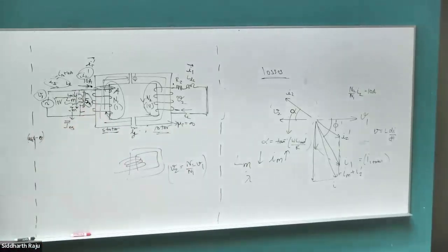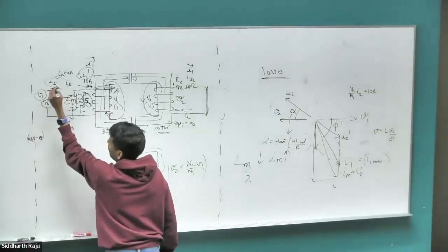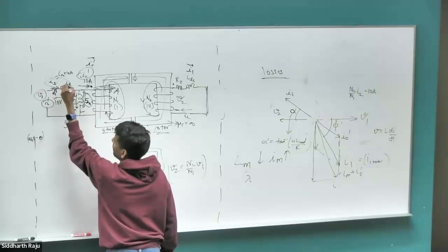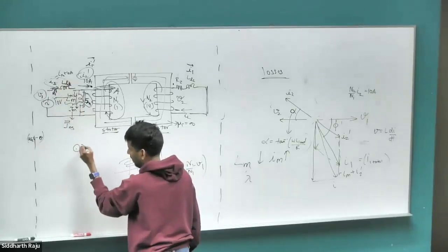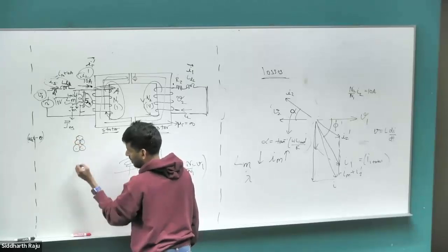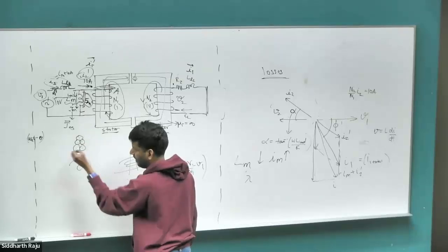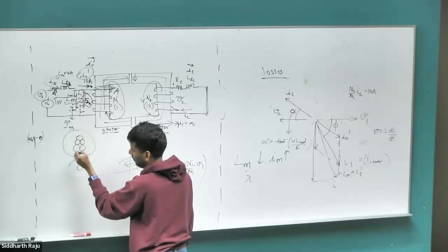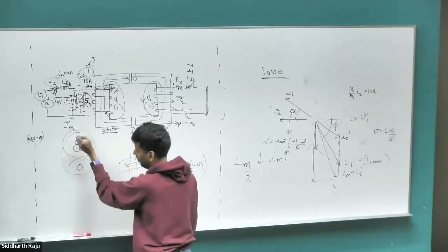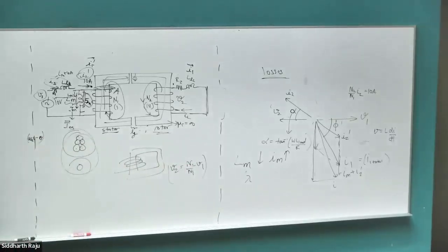If I have a resistive and inductive drop on the stator side as well, due to the stator winding resistance and then the stator's own leakage inductance, LLS, because of the same diagram that I drew there, I have some rotor bar flux that only links the rotor bar and not all of it links back to the stator. The same thing happens with the stator-rotor relationship. Some flux of the stator winding only links to itself, not linking all the way back to the rotor winding. Right? So that's going to have its own leakage drop that we are going to be modeling, and that's going to drop some voltage.